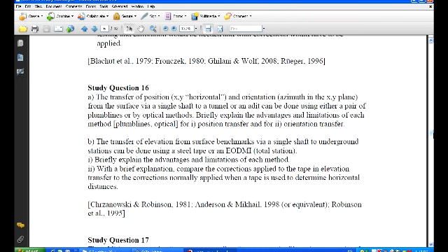readings at the surface and readings underground, and assuming that you then know the distance between the graduation on the tape at the surface and at the bottom, and therefore can add that on to the height of instrument at each level and eventually come up with a height difference. So that's relatively straightforward.